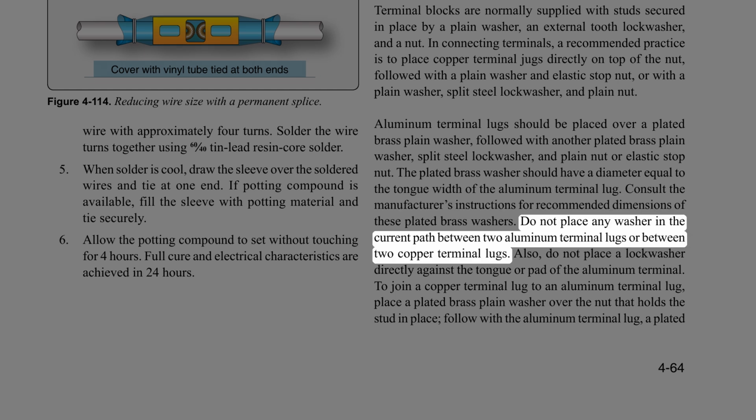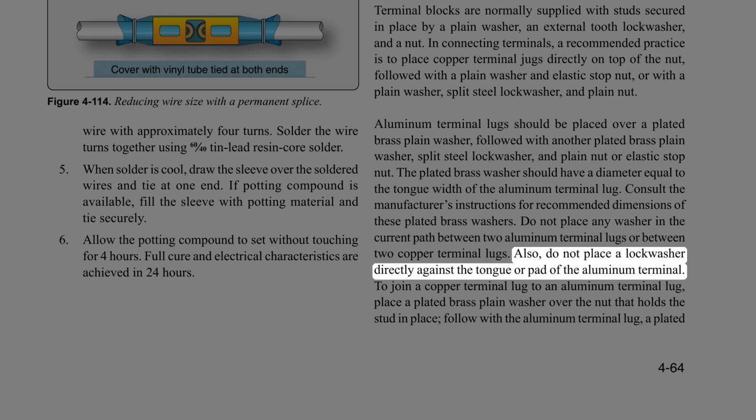Do not place any washer in the current path between two aluminum terminal lugs or between two copper terminal lugs. Also, do not place a lock washer directly against the tongue or pad of the aluminum terminal.